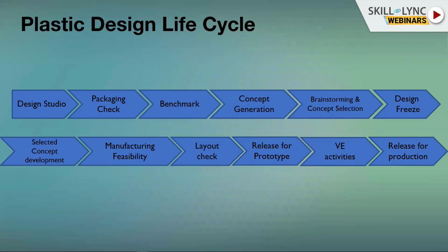And as a team, from the brainstorming, one of the concepts will be selected, right? And then that particular design will be frozen. After freezing, this particular concept will be developed. Development involves attachment features, assembly process, master sectioning, and then defining the thickness, where the parting line should be, how the assembly should be done, and what the concepts involved in attachment are, right?